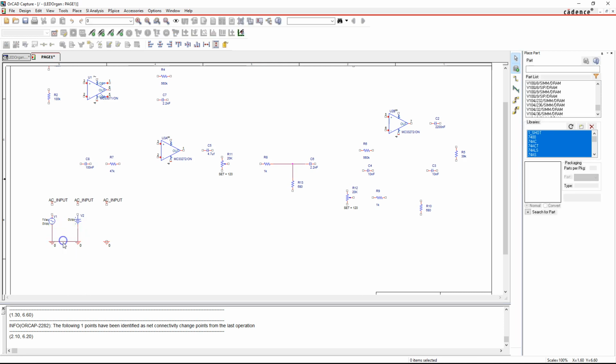Wow, okay, so I botched that connection real good. Now ground to ground is fine. That's actually a valid connection, but I don't like how it looks. So, all right. Okay, so what I'm doing here is I'm connecting these nodes to this net so that if I put these power pins anywhere else, that part of the circuit automatically gets connected to the power here.